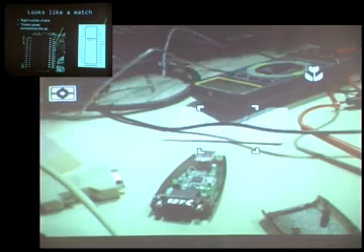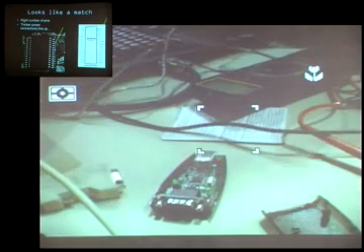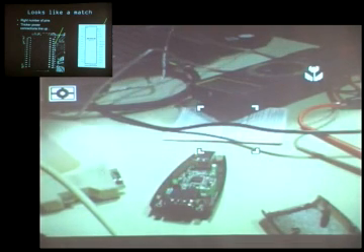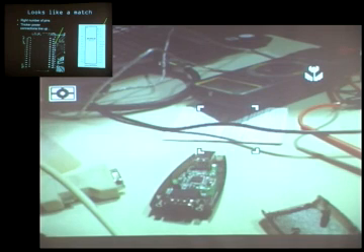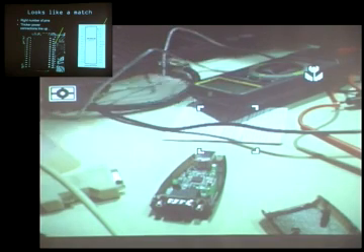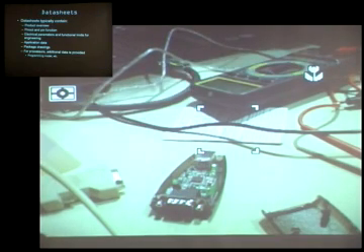Anyways, the other thing you can do to sort of make sure that these work. So here's the Max3243 pinout, and this is the ZT3243 clone. You kind of take a look at it and say, okay, where are the thick pins? Okay, there's a thick trace coming out here. Third pin from the top right, oh, that's VCC. Oh, I see a via coming here to ground. Okay, this is probably a match. You get a good feel that we're not in the wrong ballpark, same number of pins. So you say, okay, these are the same chips, go for it.